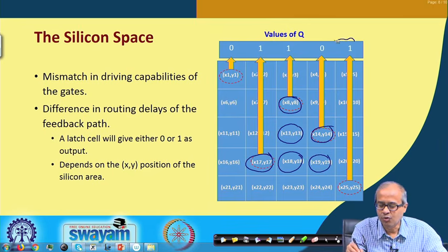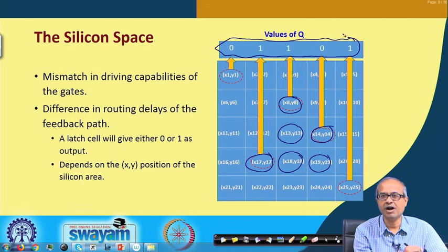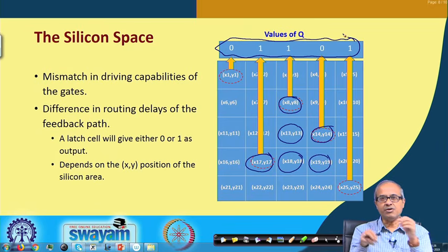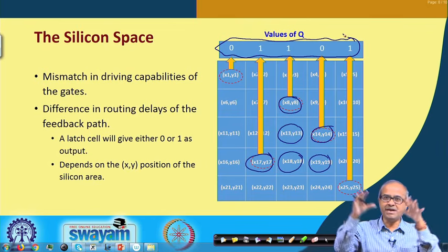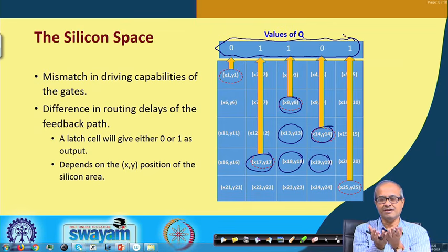So, accordingly, what will be the final values of y's will depend on how you are interconnecting them. It does not depend on the circuit, but rather on how you are making the interconnection, where you are placing which gate. In an FPGA particularly, you are not fabricating anything, you are mapping a design into a programmable fabric. So where you are mapping and how you are interconnecting will determine the final challenge response pair of that PUF, in terms of the SR flip flop that we have just now talked about.